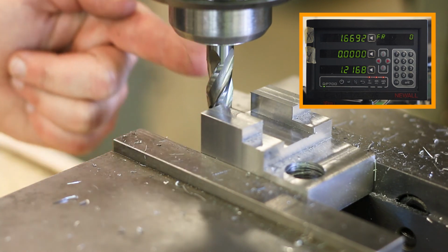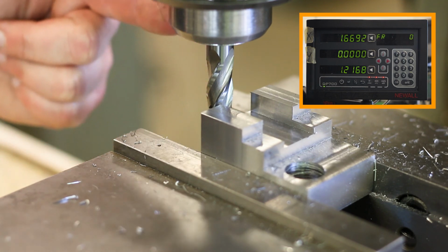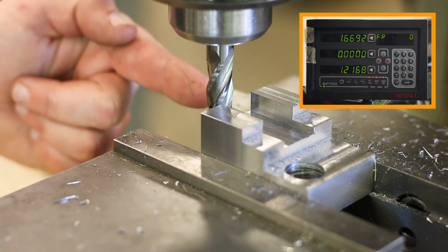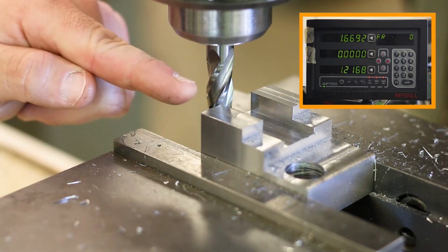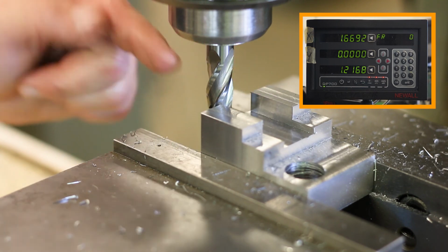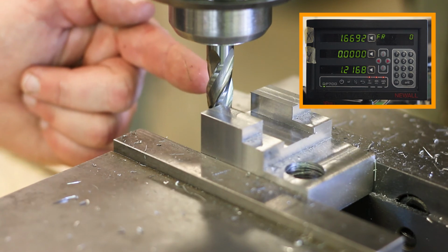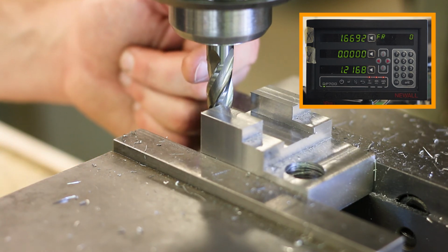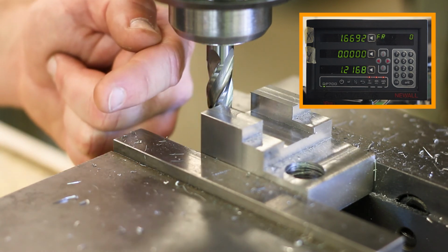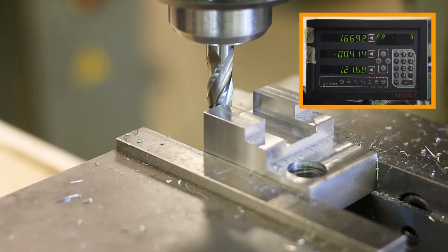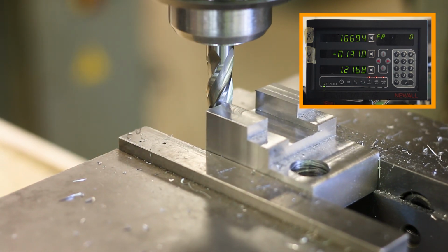The amount that we're going to move over is equal to the center plane offset, right? So if there's a 1 thousandth of an inch difference, the center plane offset is half of that, which is a half thousandth of an inch, and we're going to adjust that in the minus direction on the digital readout. So this direction, right?